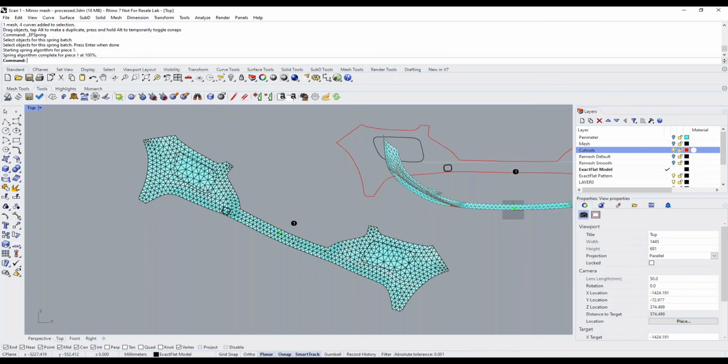And so the only nuance when you deal with metals is the plane of flattening. Is it the inside surface, the outside surface, or is it the midpoint or some other point in between? That's a consideration that you need to take into account. If it's thicker metals, if it's thin metal like a sheet metal, it'll work just fine. So if you have a question about metal forming, Shane, then we're happy to talk more about that. But yes, it can be used in metal forming.